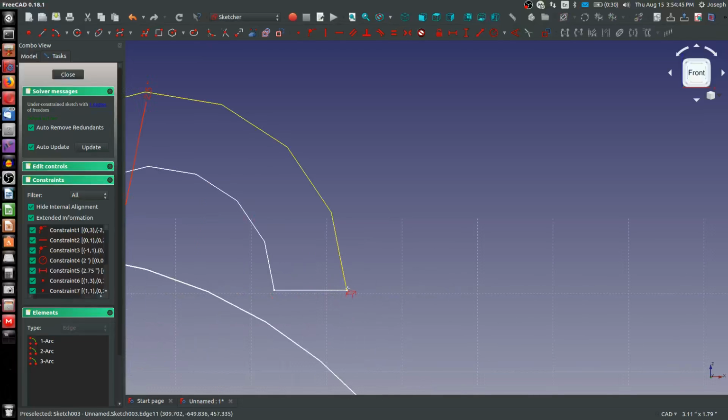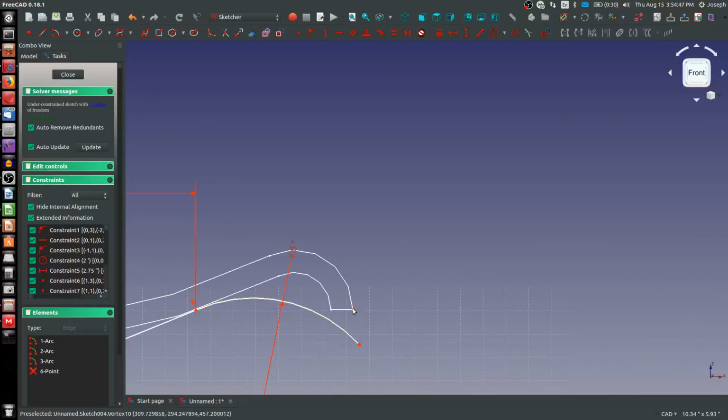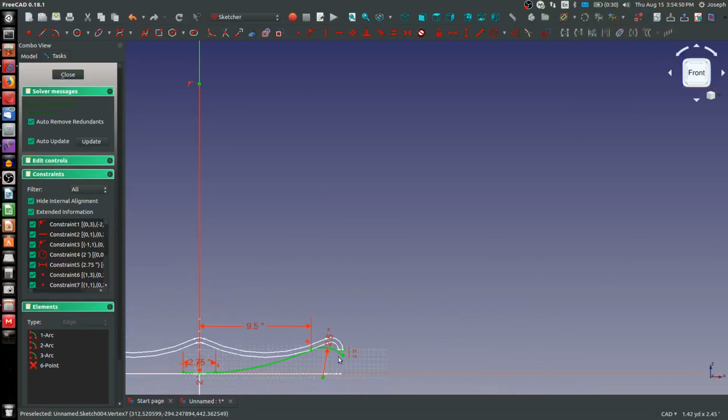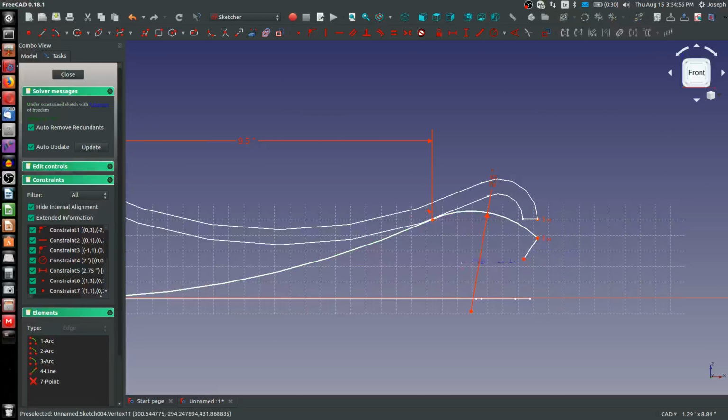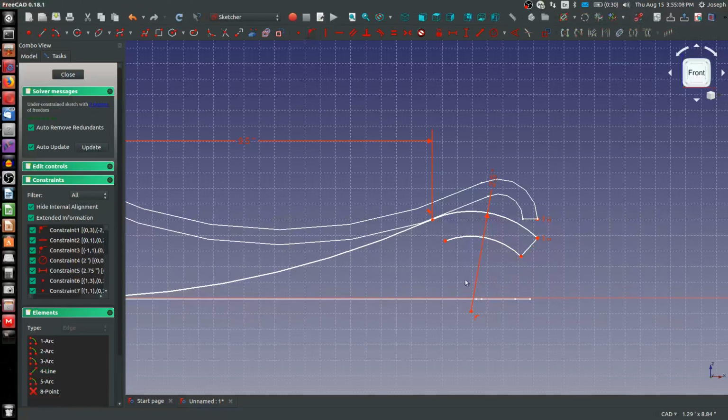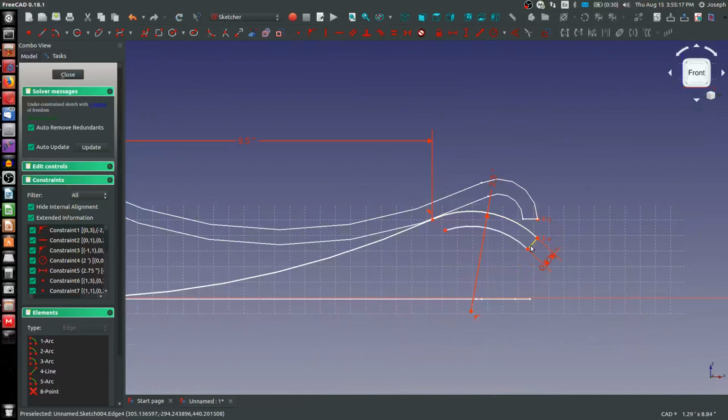So I'm going to import the widest point from our last sketch, add in a vertical relation, and that gives us another full constraint. Add a point here, or a line rather. If I make that coincident with the center point, then we know that we're 90 degrees. I'll choose this dimension to make it 0.375 inches thick.